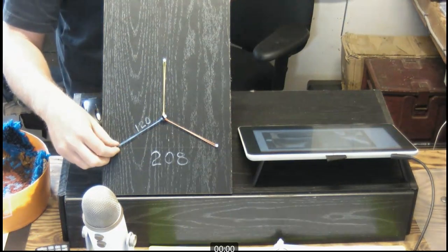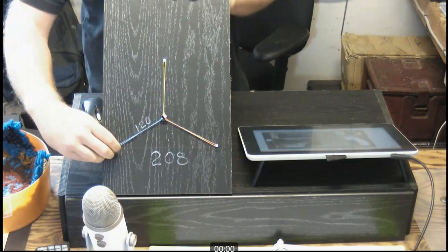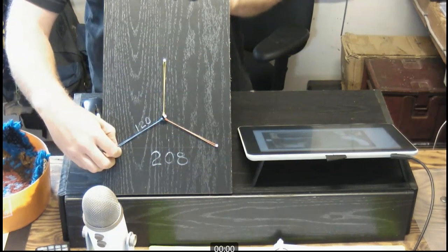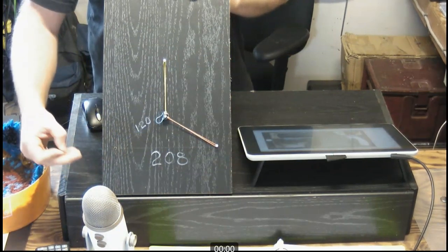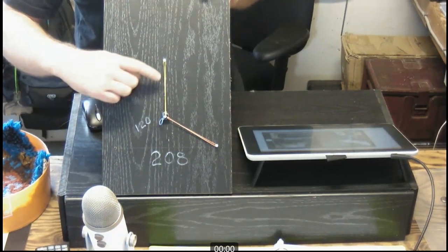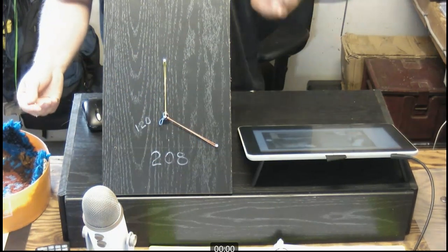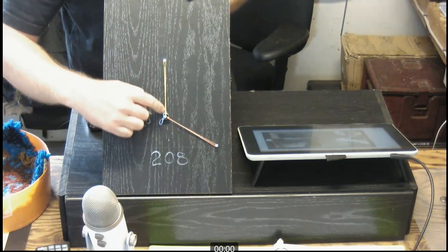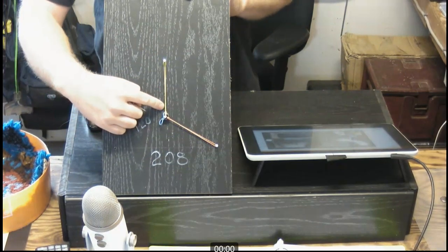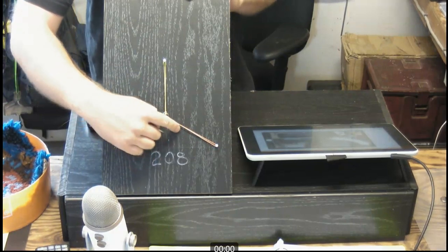And inside of your problem, the open line with a neutral connected to the load, watch what happens when I lose my line. They show in your example that we're losing line C. As soon as I lose line C, because we've got that neutral connection, do these two change? Absolutely not. You can see that they're still stretched out over there, which would mean how many volts is still across each of these? It's still going to be 120 volts across this one and 120 volts across this one.